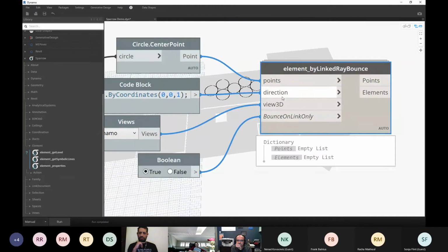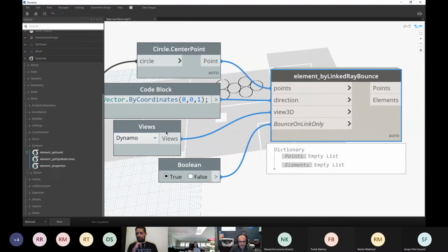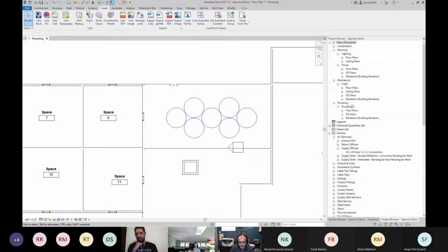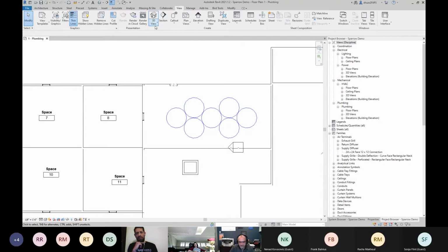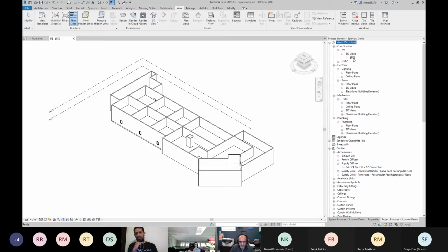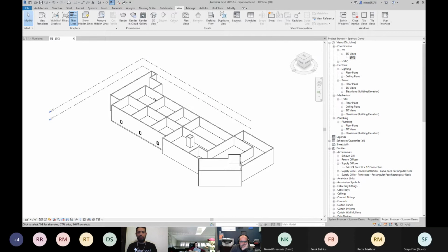I'm going to answer a question in the meantime. Yeah, please help me. So it's a follow-up to the previous question. So yes, definitely. Once you get the geometry and you've checked through an if statement or a conditional statement what type it is, in the same conditional statement, once you find a mesh, you add it to the mesh list, and once you find a solid, you add it to the solid list.